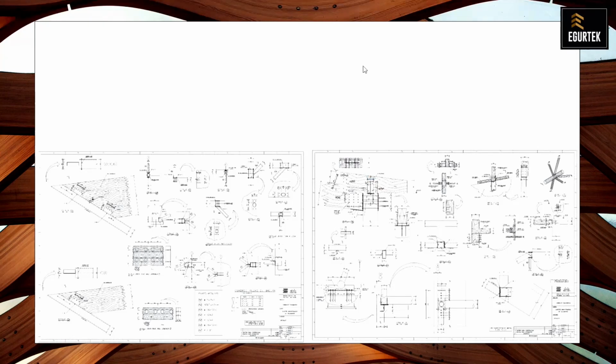And well, we found that the engineering was very interesting too, because this is made of reinforced concrete and steel and wood. There were many joining parts. And this is a second project where you can see these elements, once they've been assembled on different kinds of material: steel, wood, concrete. We have lots of earthquakes in Chile, so this is why these fixations can slide. They can slide up to 10 centimeters, so everything has been made mobile.